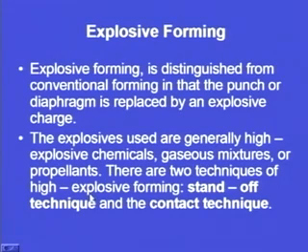There are two techniques of high explosive forming. First one is the standoff technique and the second is the contact technique. So, we have seen in this particular slide that explosive forming is a process which has replaced, in some particular application spectrum, the conventional forming processes. The punch type of arrangement is absent, and we make use of an explosive charge which is used to change the shape of the sheet. Different types of explosives can be explosive chemicals, gaseous mixtures, or propellants. Depending upon the requirement we will choose our explosive.